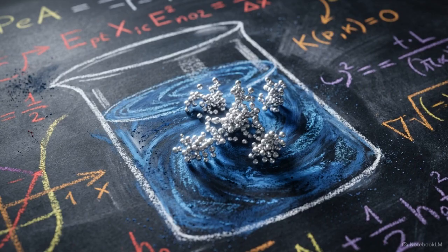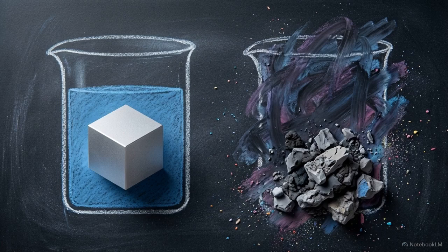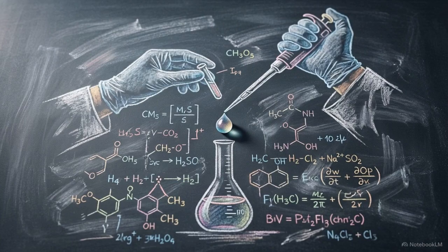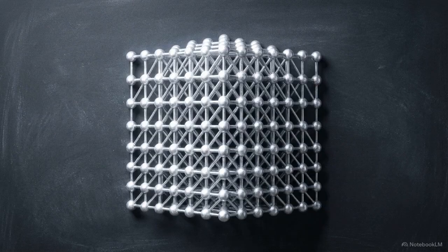Creating this environment introduces a difficult chemical paradox. The aqueous solution must be thermodynamically unstable enough that it readily reduces metal ions into solid form, yet kinetically stable enough to prevent those ions from spontaneously precipitating into a useless metallic sludge. To maintain that balance, we have to construct a perfectly tuned electroless system from first principles, adjusting the exact concentration of every molecule. Eliminating the power supply shifts the burden of process control from physics to precise chemical determinism.